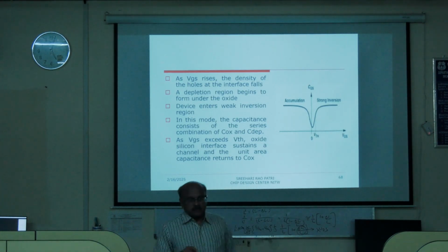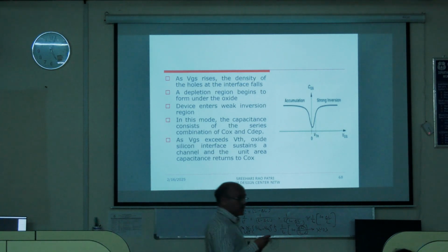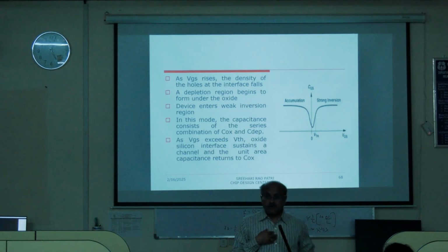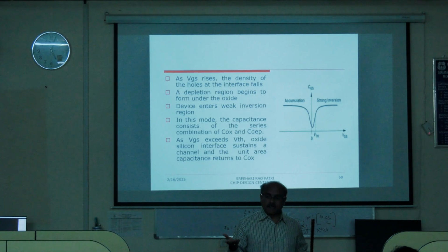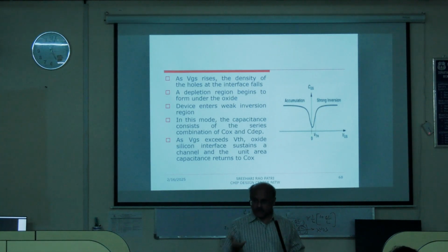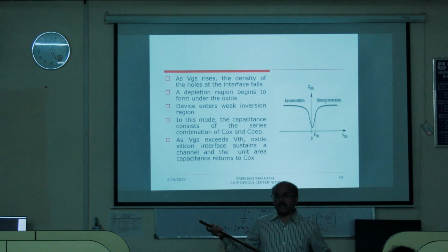Now we can see that a simple MOSFET is a regulated capacitor, and I can always have a capacitance value of my choice by choosing the appropriate W value, because the capacitance is a function of the area, Cox times W times L. The larger the WL, the larger the capacitance. Therefore, I have a beautiful capacitance in my hand.